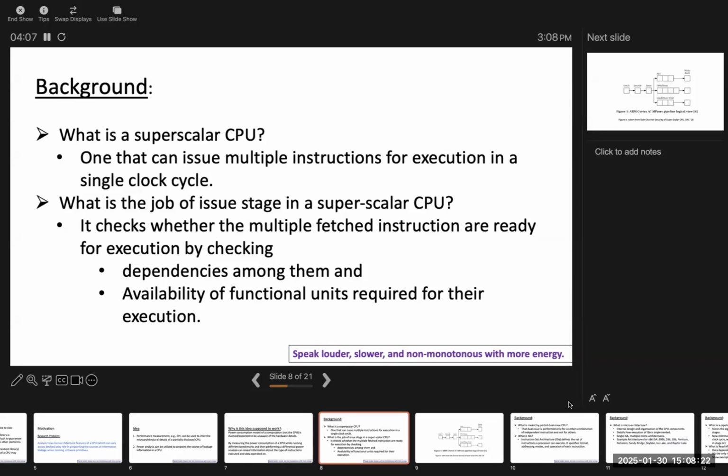And let's say that when I execute this instruction, it takes 10 time units. To make it simple, let's say 10 seconds, right? And let's say the instruction execution starts only when the positive edge of the clock arrives. Then it continues, right? So these are 10 seconds. And then on the next clock cycle, the execution of the next instruction starts, right? Let's say it is my add instruction. So the add instruction takes 10 seconds, which means the next instruction has to wait for 10 seconds before it can be executed, correct? Everyone with me?